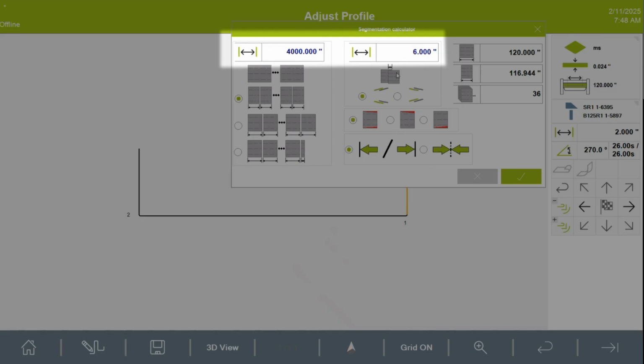There. The next thing we want to do is say, how much overlap do I want? What this means is how far do I want one piece to fit down inside of the other? It needs to know this so that it can make the male and the female side of it wider or more narrow so that it can have a larger overlap. Okay. 6 inches, 4 inches are pretty normal. All right. Just because you assign it 6 inches doesn't mean you have to overlap that part by 6 inches. You can leave it at 2.5 if you want. It's just there so that the machine can calculate the width so that you can slide the part as far as 6 inches if you want to. All right.